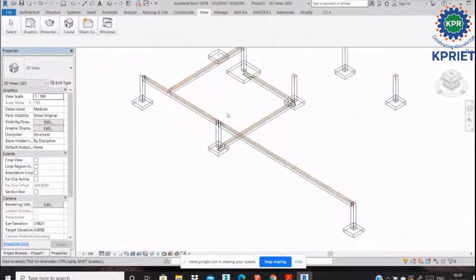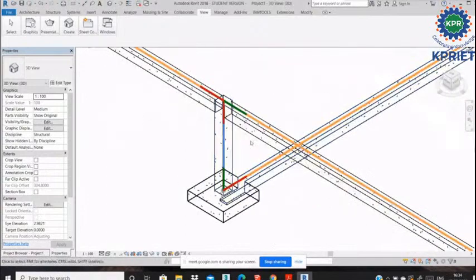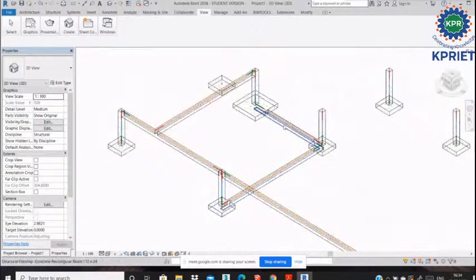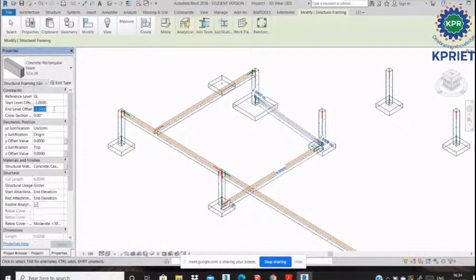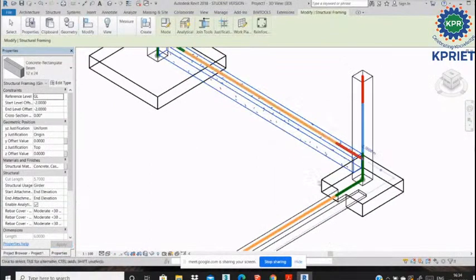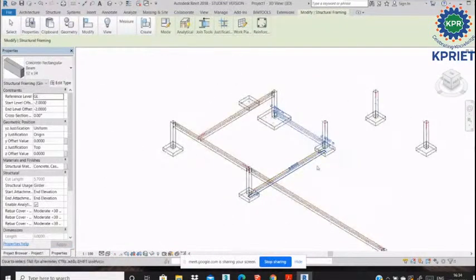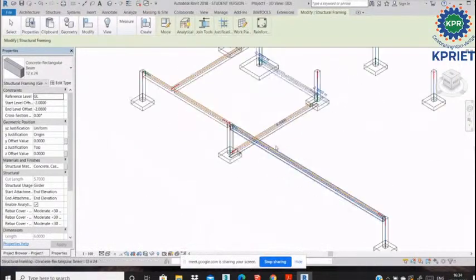Now let's understand how to create the main beams and this type of ground level beams, plinth beams. To create the plinth beam, simply click this, which is 2.5, right? You click this 2 meter, right? Now understand. Now you see, click this, right? I would say it is automatically created, right? This is a ground level pedestal to pedestal raft beam, like a plinth beam, above the ground level, right? Now the beams are also easily created, right?